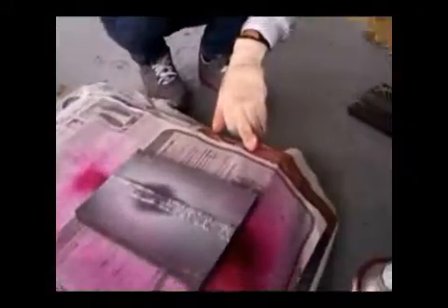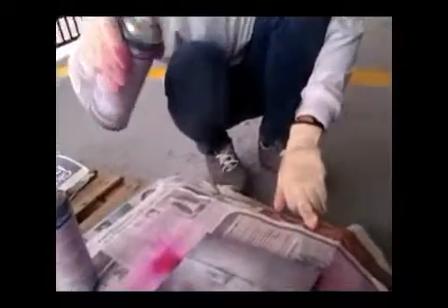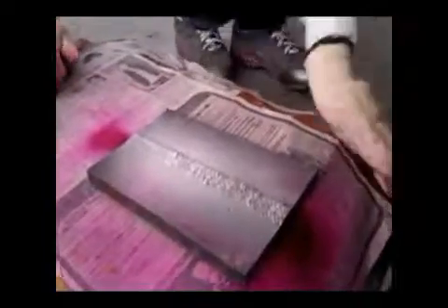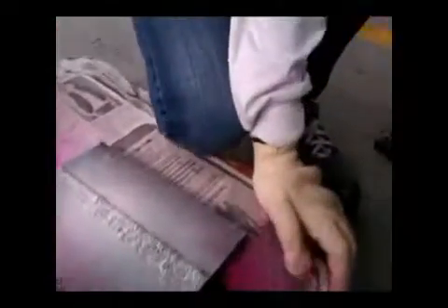The developer draws penetrant from defects out onto the surface to form a visible indication, commonly known as bleed out. Any areas that bleed out can indicate the location, orientation, and possible types of defects on the surface. Interpreting the results and characterizing defects from the indications found may require some training and/or experience.